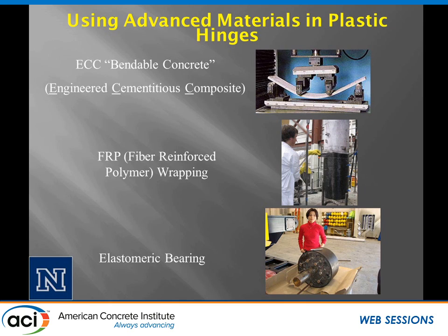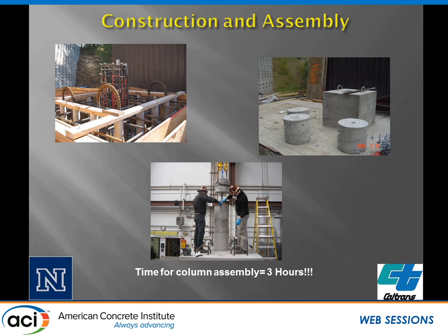We've used these extensively in retrofitting, but maybe we can use them as part of traditional construction by applying them in these areas where we think that they could be most effective. And then maybe we can put some sort of elastomer in this system. What can we do in order to, again, introduce some flexibility and mitigate the amount of damage that's occurring in the system?